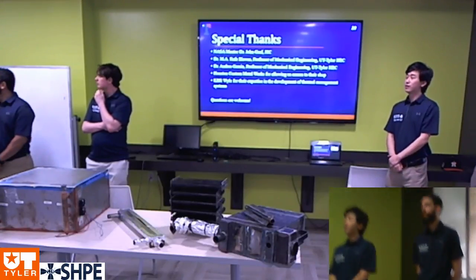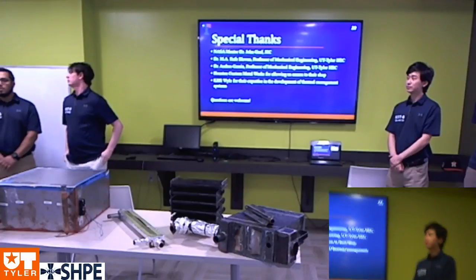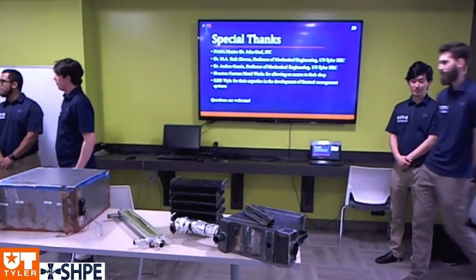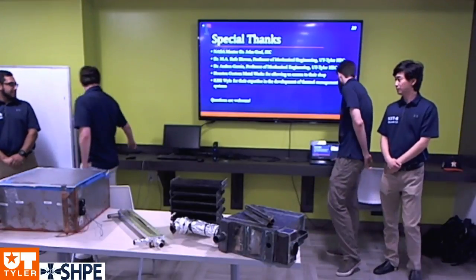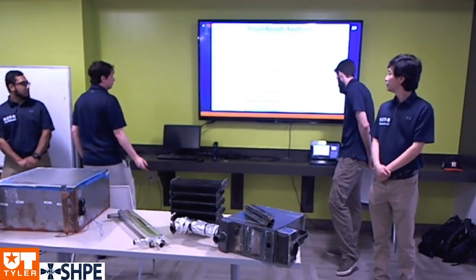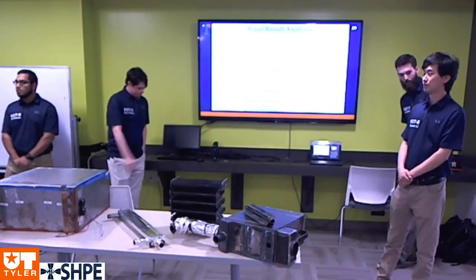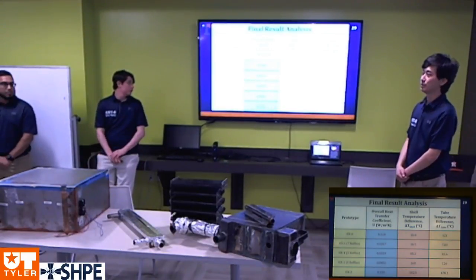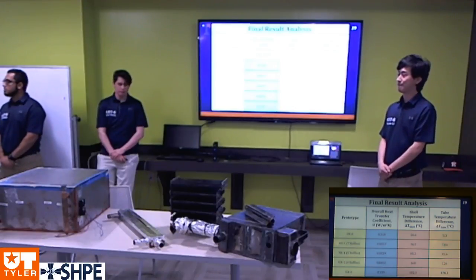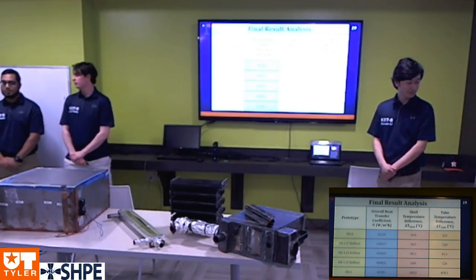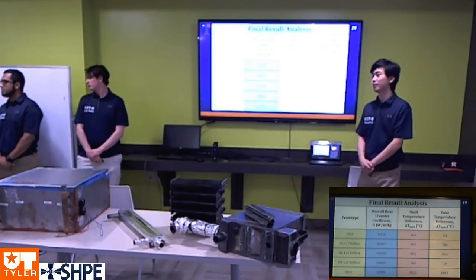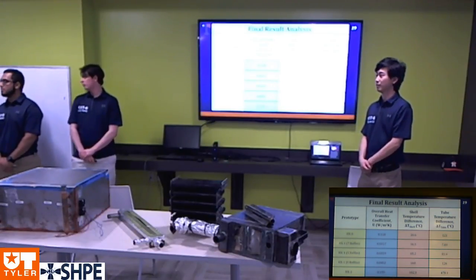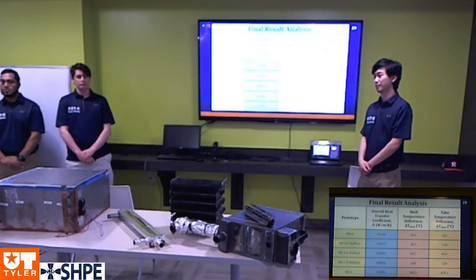The temperature difference we're getting. So if you look at the chart, our temperature difference for the initial one was only, can you go back to the slide? There is a high temperature. Yeah, so for our shell, this one right here, we were only getting, you can see, like 26 on the shell side. So we were pumping in about 150 degrees Celsius, and it was only exchanging around 25. Our last one, I mean, we were pumping in a higher temperature, but we were getting almost a 190 to 200 degree temperature difference.